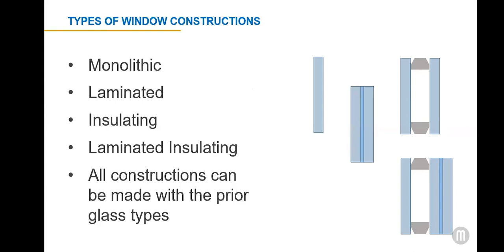Laminated glass is multiple layers of glass bonded together, typically with PVB. Usually laminated glass is 2 layers of the same thickness of glass and a single interlayer. The interlayer holds broken glass together in the event of a breakage. Glass can be annealed, heat strengthened, or tempered.